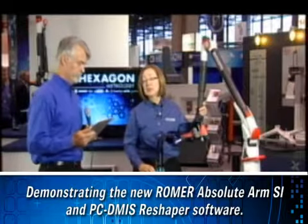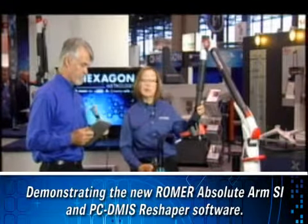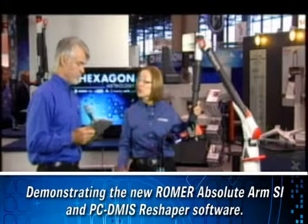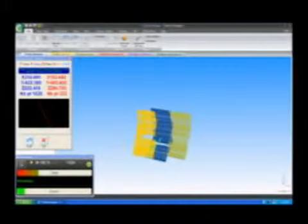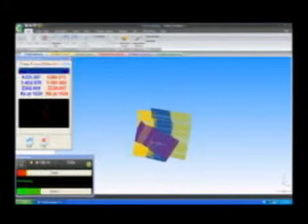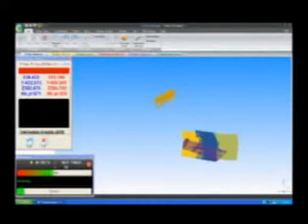It is a three-dimensional point cloud processing software that I can use to generate a high-quality mesh and also to create surfaces and B-splines that I can export to a CAD model. I like all the different colors. Yeah. What are they for? What that does is it actually creates each scan pass as a separate color. That just makes my job easier when I'm editing the point cloud data later on.